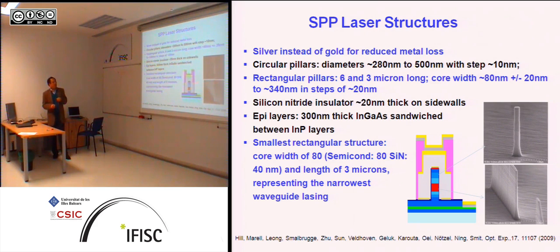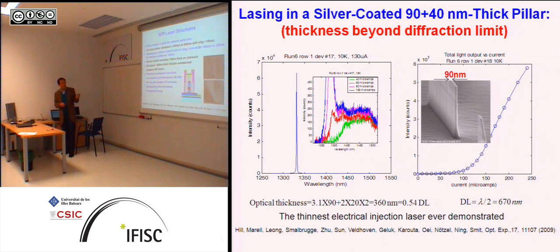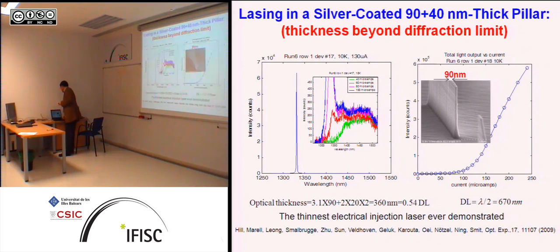It's thin, yeah? We coated it with a dielectric, silicon nitride, about 20 nanometers on either side of this pillar. And then, of course, we evaporated silver. Basically, it's silver covered. This is shown schematically here: this is the P contact, N contact, this is the semiconductor pillar, and this is the active region. The black region is silicon nitride. This is what we call a metallic coated laser. This is actually the thinnest one we could get to lase, about 90 nanometers.